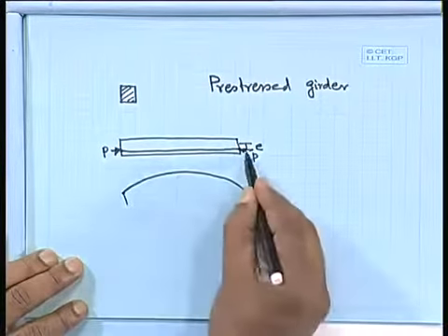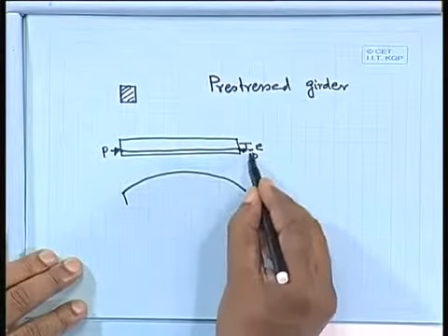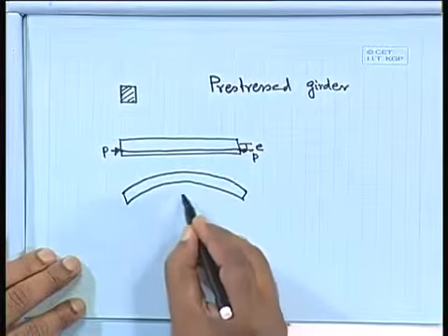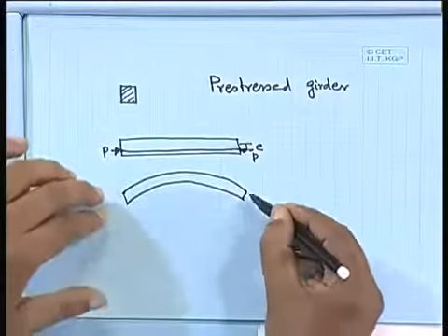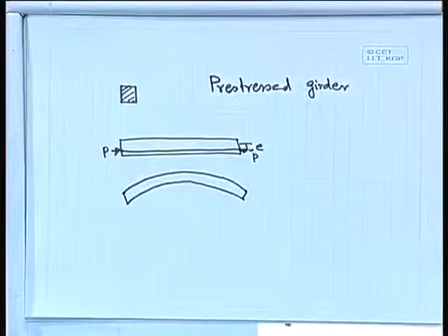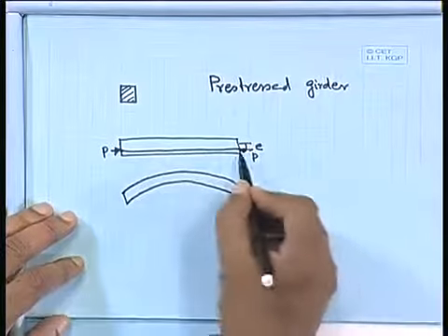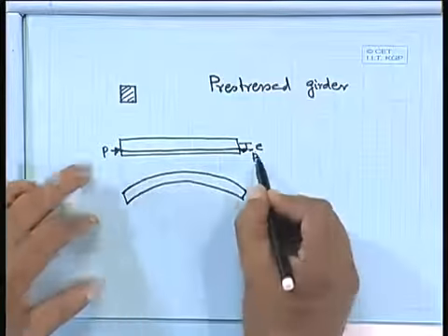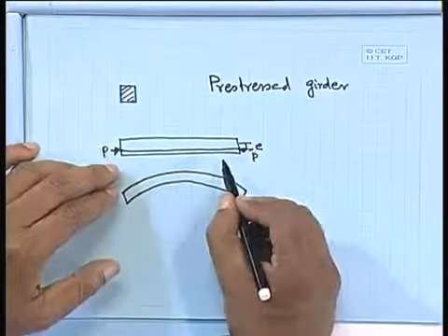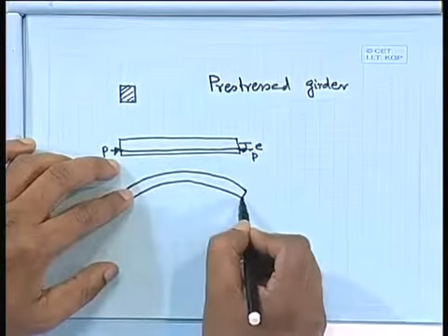Due to bending, due to the moment developed, there is a moment developed here. So initially it will be like this. Not that much, but anyway, it will try to bend in this fashion, because of how you are applying it. I am not putting it directly in the center. Instead, I am intentionally giving it a certain eccentricity. So it will develop a moment, and also an axial force. So what will happen? It will make it like this.